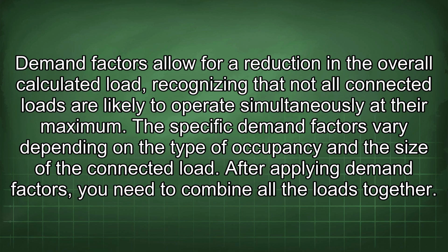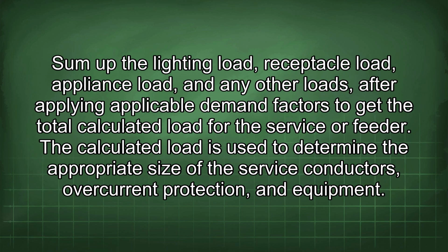The specific demand factors vary depending on the type of occupancy and the size of the connected load. After applying demand factors, you need to combine all the loads together. Sum up the lighting load, receptacle load, appliance load, and any other loads after applying applicable demand factors to get the total calculated load for the service or feeder.